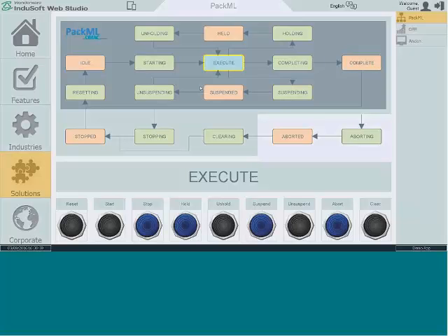And the idea behind PackML is to allow different packaging equipment to use a common language. For example, if the machine is stopped, is it stopped? Is it halted? Is it stopping? What is the state of it? And it commonizes that language. And I've actually seen examples where some Allen Bradley PLCs were talking to Siemens PLCs using PackML, and using that commonality, were able to share information between, again, dissimilar brands of PLCs. So this PackML template is included. Feel free to take it and use it.